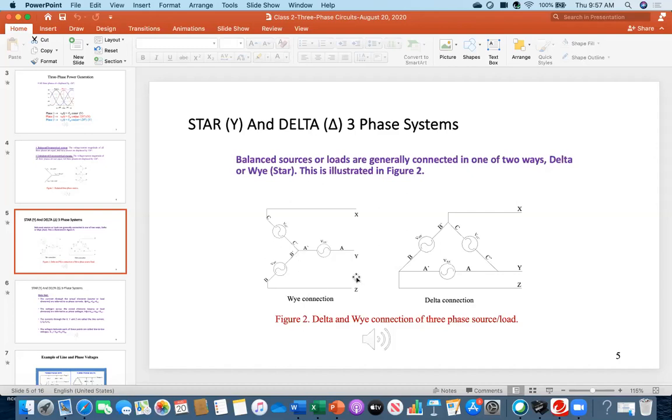For example, industry can use the three-phase with neutral system. At our home, we can use the single-phase and neutral system. You cannot use this at your home, nor can industry use it. But in this case, you are saving the cost of the neutral line. You don't need the neutral line. So the question comes: where to use the delta connection? There are certain places on the transmission line and distribution line where customers don't need to use any power. In those places, use the delta connection just to save the cost of the neutral line.